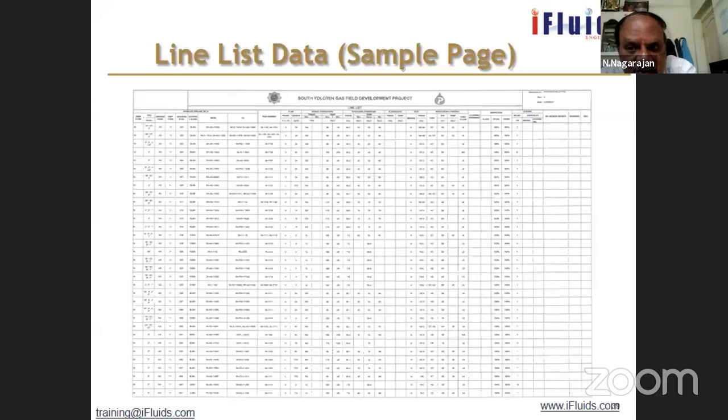Density, if it is a liquid line, say liquid density, etc. It can be elaborate. We can put all the details about that particular line, and then also you will say what is the test condition, whether it is a hydro tested line or pneumatic tested line. Then what is the testing medium, that is the type of testing, and what medium is used for testing.